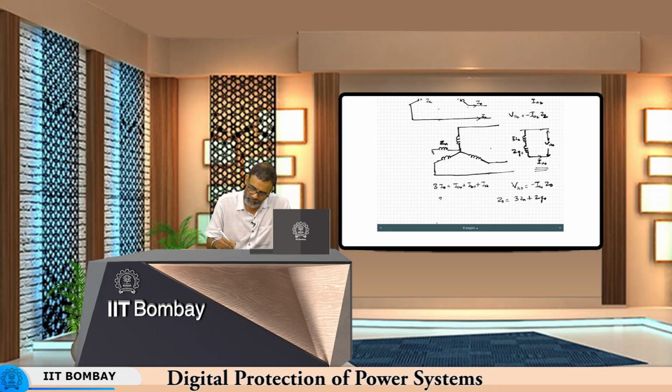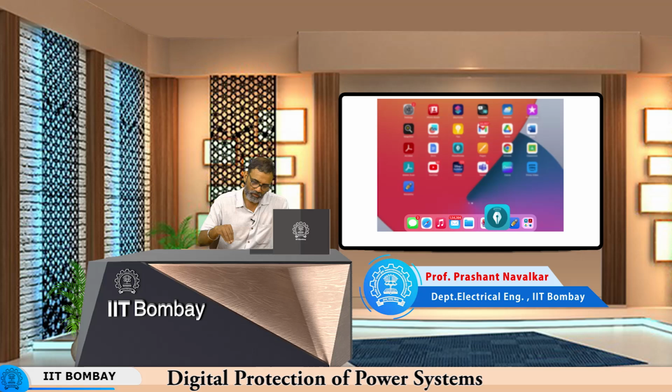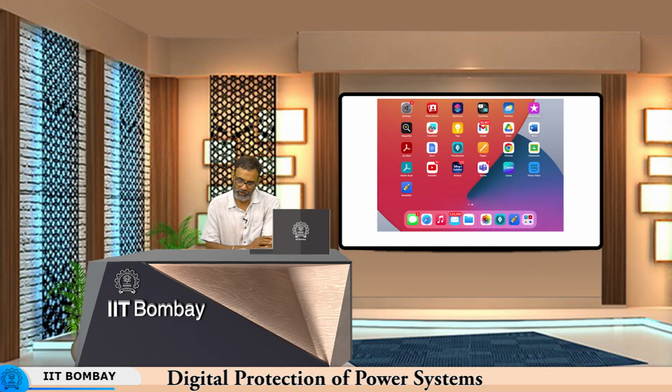So, the equivalent drop, which is 3 I0 Zn, is then shown as I0 into a 3 Zn drop. So, that is why this 3 Zn appears in the zero sequence network. Okay. So, we will stop here and continue next time with the other network components.